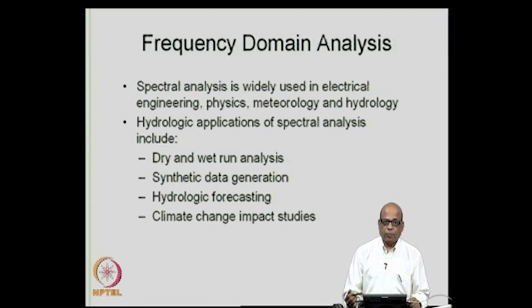Rather, we will pick up directly the expressions that are available and see how we apply them to a hydrologic time series, how we interpret the results, how we identify the periodicities, how we check the significance of the periodicities so identified, and what we do with these periodicities in subsequently building up the time series models.